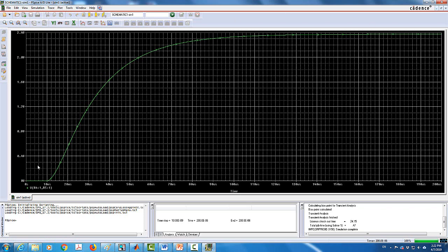You can see that early on the two time constants are taking effect as the voltage across the capacitor starts from 0, but then eventually S1 starts to be more dominant, because S1 is the slower time constant. And then we see that at t equal infinity we haven't reached the 2.4 yet. We're a little bit less than the 2.4.